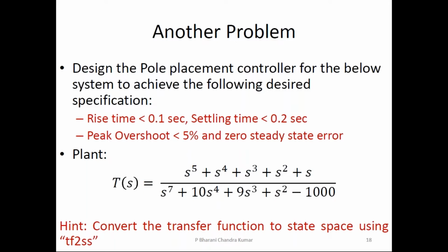I don't have the paper now, but I will explain what is in that paper. This is the nonlinear plant. The nonlinear plant is given in that paper, but the linear ABCD matrices are not given. The first thing is, from the nonlinear plant you have to find the ABCD matrices. How to find them is the Jacobian approach.